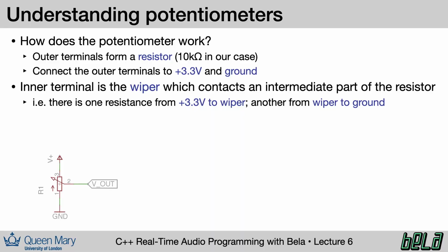In these circuits, we're using potentiometers, or POTs for short. Let's talk a little bit about how these work. They're sometimes described as a variable resistor, a resistor being something that resists the flow of electric current. The essential idea is that the potentiometer contains inside of it a ring of partly conductive material. When you turn the shaft, there is a metal wiper which moves back and forth along that conductive strip, and it effectively divides it into 2 pieces, one on each side of it.